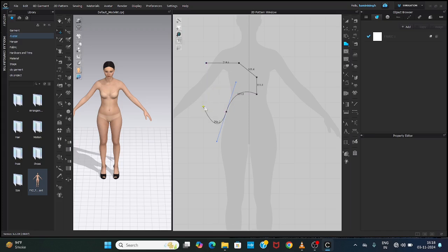This is more like the pen tool in Illustrator. If you have used Illustrator, you can easily use it. What to do for making a curved line? Simply click, then don't leave the button and drag, and practice to control the handle.